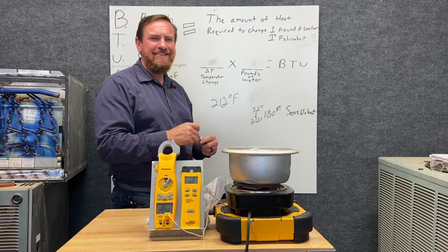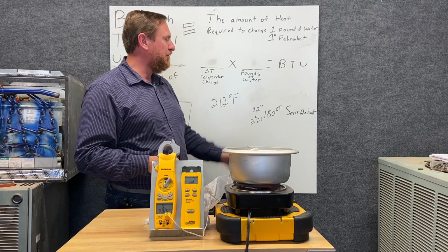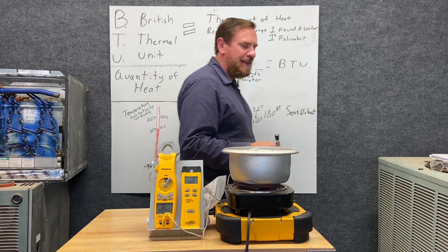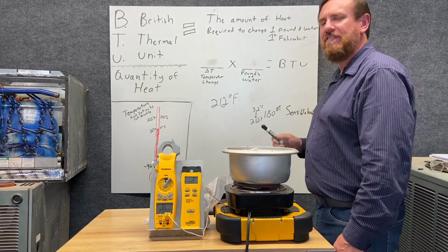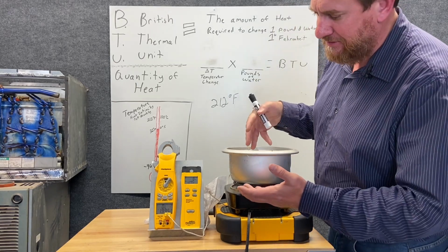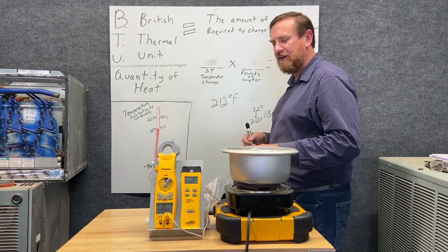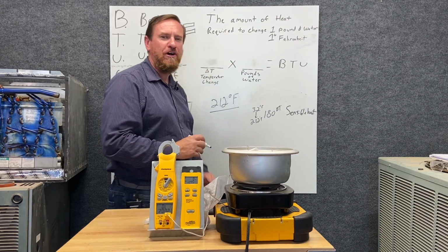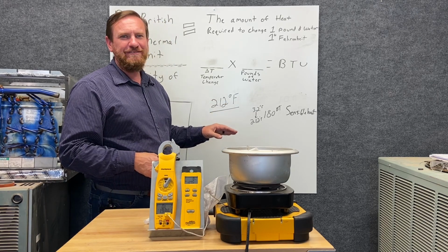And we raised that temperature pretty fast. Within a few minutes, we went from 32 all the way to 212. 212 is going to be our key number here. This is what we call a saturation temperature. So all the way up until now, we had sensible heat. Water is boiling, changing state from liquid to vapor. You can physically see it boiling, but our temperature is still going to be at 212 degrees Fahrenheit. This is where we change.